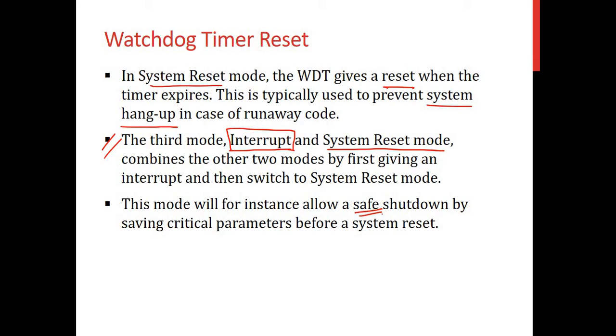But again, this may or may not work, because when we say the watchdog timer is triggered, something has gone wrong. It could be a total timing failure, in a sense that some task was hogging the entire CPU, so that the watchdog timer reset instruction could not be executed. In that case, when I generate another interrupt, it may be able to execute, but it's not guaranteed, because the system is already in a questionable state.